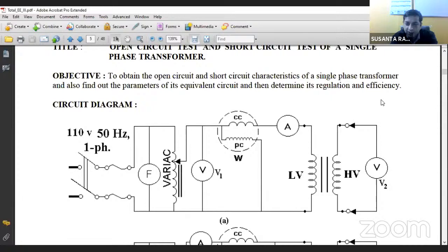The second reason is that the current which we expect in open circuit is very less, because the circuit is open. If the circuit is open, then how is the current flowing? The current will flow in the open circuit, which is also called the no load condition of the transformer. The current flows in the primary coil. Here, the primary coil is low voltage because we have connected the supply at the low voltage side. The primary current will be very low. And why?